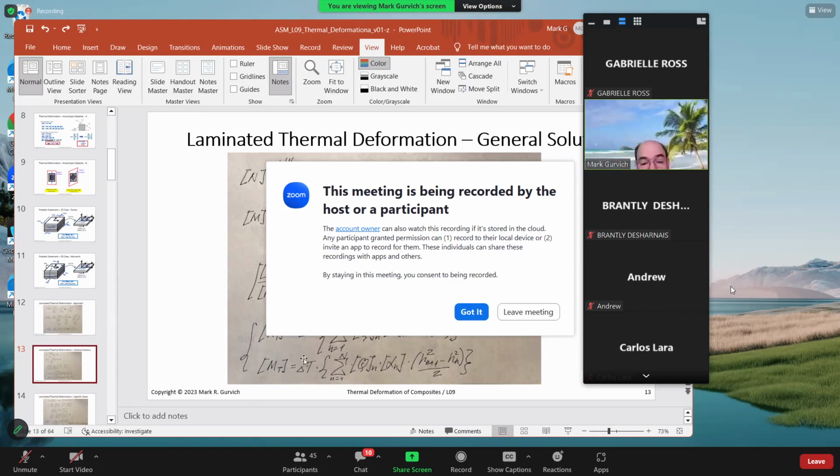In this situation you will not use delta T outside of the integration, but put delta T for each layer inside. It will be the same approach, but you take into account that the temperature for each layer could be different, especially for space applications, where it's quite critical.